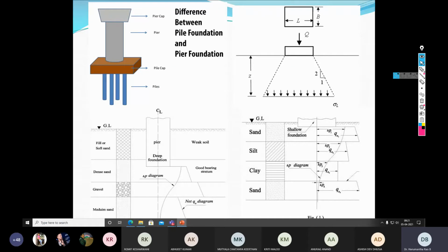Now if anybody asks you to draw the variation of the stress, right beneath the footing there is an immense amount of stress development, which is called the incremental stress, or delta P. There is another terminology we have also seen: initial effective overburden pressure, or initial effective stress, and increase in effective stress. Initial effective stress is the load because of the self weight of the soil, while increase in effective stress is the stress caused by the construction of the footing. So that's the difference. Here you can see the increase in effective stress is maximum right at the footing, and as you go deeper and deeper, it becomes almost zero.